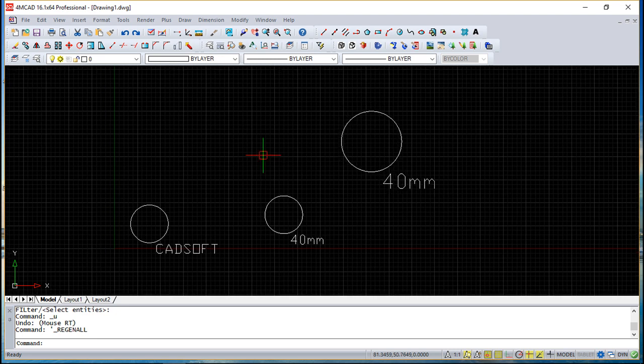But basically, this is the idea to work with the attributes. This is a very simple example, but you can use this to extract information from multiple points or multiple instances that you have inside your drawing, and it is very interesting and very important, the ability to extract this information for a database or for a file which can be manipulated outside the program.